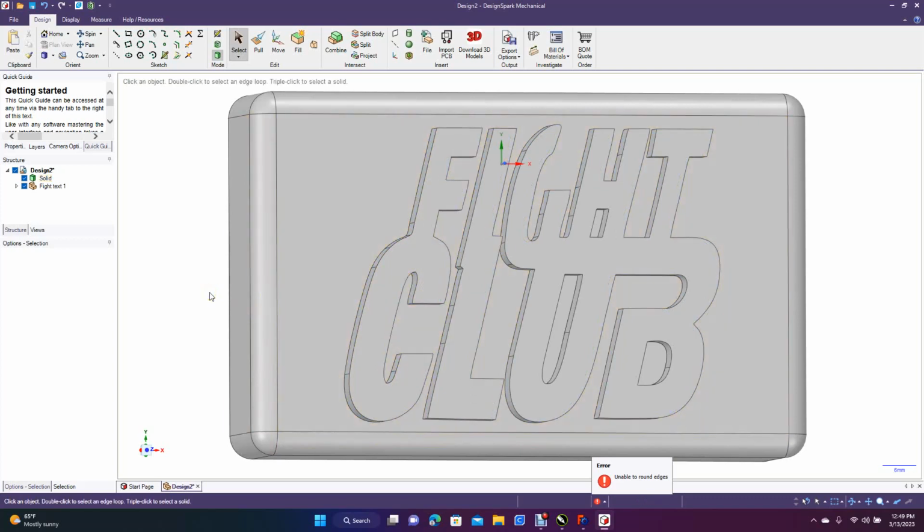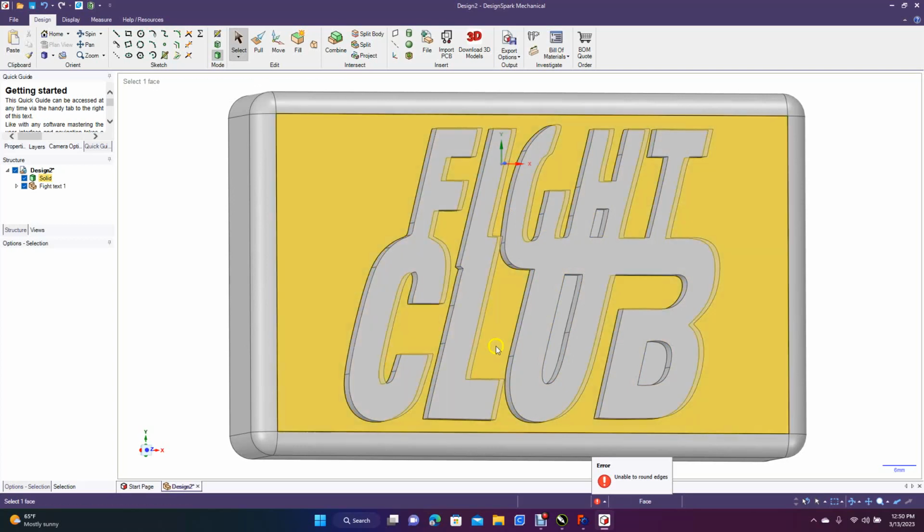The only way that I know that you can make sure that doesn't happen is you would need to take your SVG file into a CAD program. Like, you could use Freecad. I don't know how to do it in Freecad, but I know that you can do it. You're going to take your SVG file into Freecad, and then you're going to select everything, and you're going to create what's called a polyline. So what that does is it takes all these little individual lines that I'm pointing at, and it makes it one line. So then you would be able to add your chamfers or fillets to stuff.